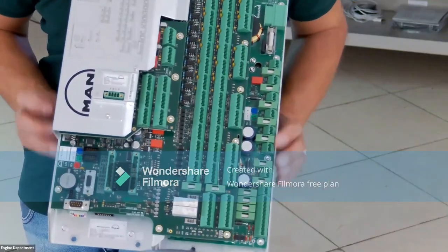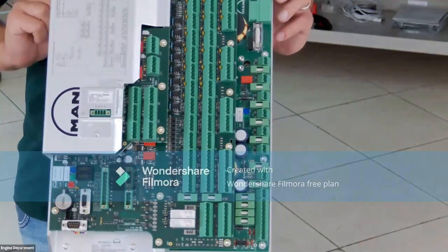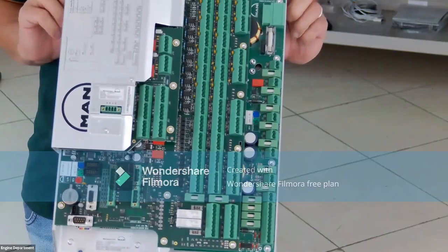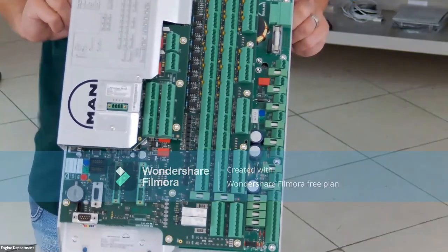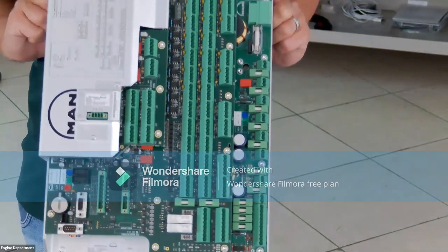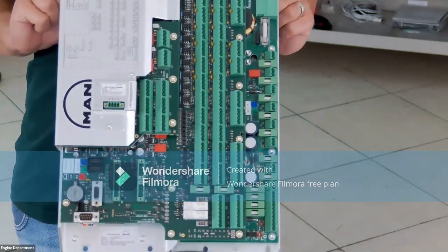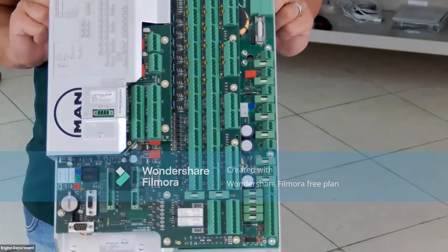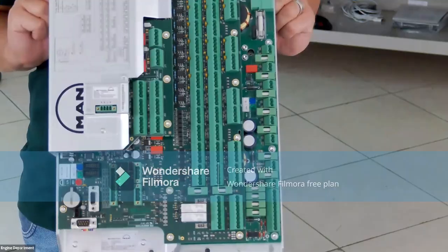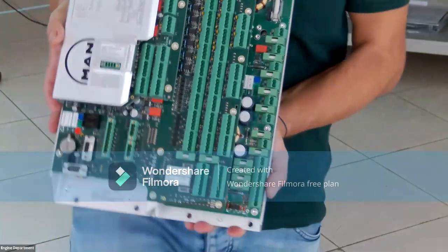But as I told you, if it's an engine interface control unit or an engine control unit, you can reset them underway at the actual engine speed, because they are duplicated controllers, so nothing will happen. The respective controller will reset and take the control, if it's unit A. But if you reset either controller which controls the mechanical equipment, they will take control suddenly at the actual engine load. So if you have high load, it will create some shock on your engine. So before or during the reset, the engine is required to be in slowdown, operating at low speed. Clear?